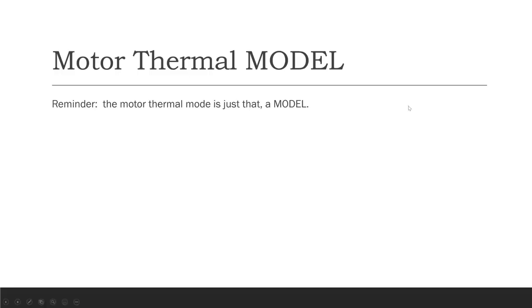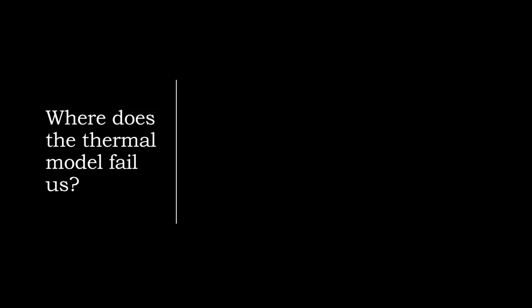And again, the motor thermal model is just that. It is a model. Without RTDs, it does not give us any real-time data, any real data as far as the temperature goes, which is what kills our insulation. Okay, so where does the motor thermal model fail us?